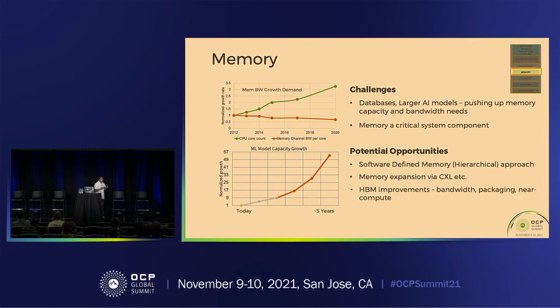So looking at current accelerator-based modules where we have HBM, that is not going to be sufficient to continue scaling. So we should consider alternatives where we extend and exploit the hierarchical nature of memory. Memory systems traditionally have always been a pyramid where we have high bandwidth with lower capacity, and then grow in terms of capacity and reduce in bandwidth. So this needs to be more natively thought about when we build applications and exploit them.